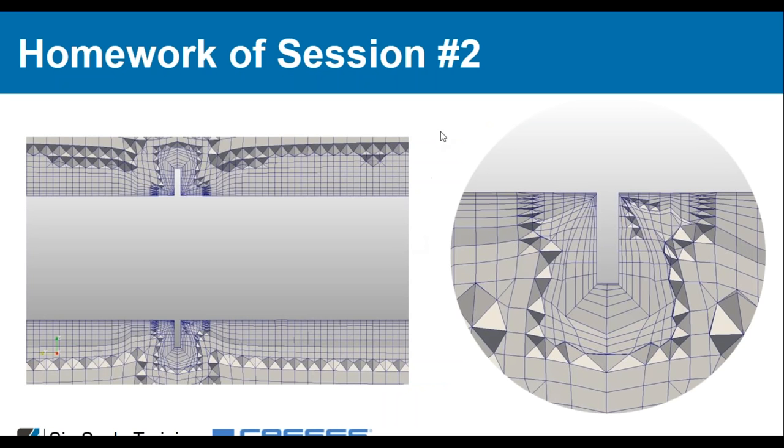Another very important point, which was discussed and still is, for sure, the layers near the wall. Here you can see, for example, the cut in X direction. This is the upper side, this is the lower side of the main plane of the front wing, and here we can see the separator in the middle of the wing. Here you can see the layers, and as I mentioned, you have this logarithmic growth of the height of these elements. You can see how good these layers are; they really follow the whole surface. And here we have a detail where you can really see how it's expanding.